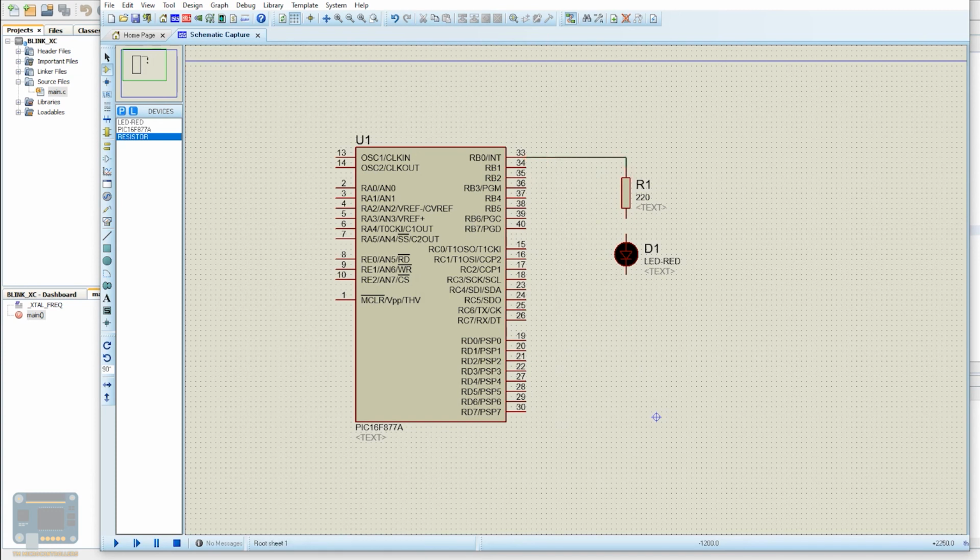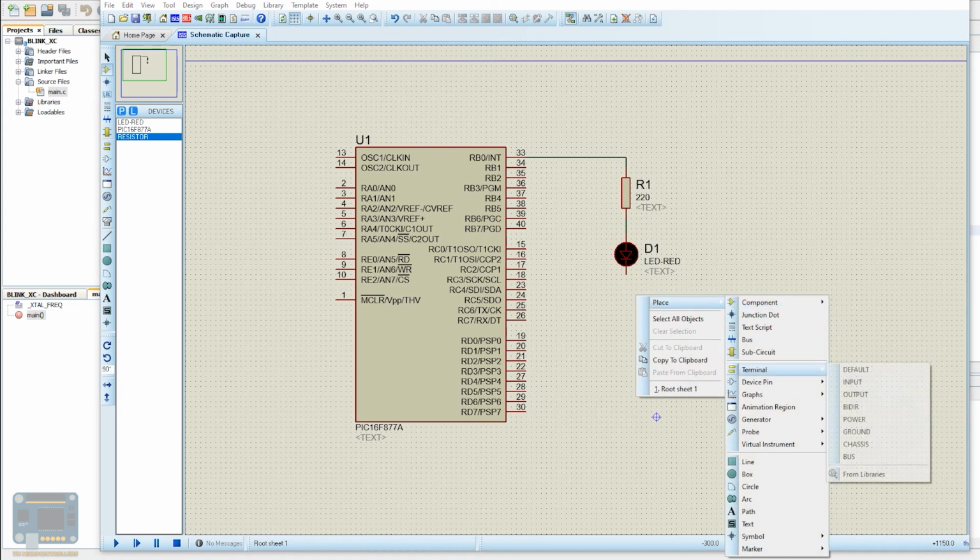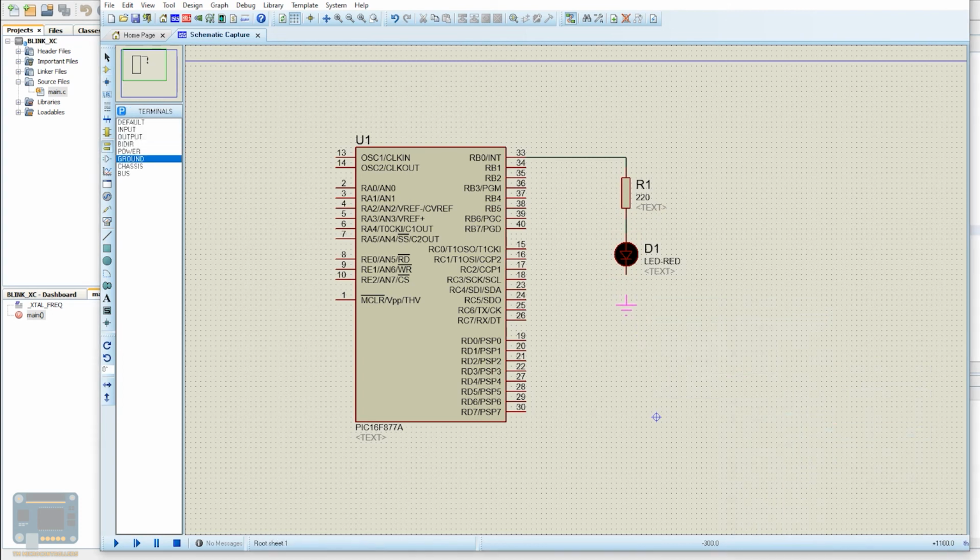By the way, the pin could produce around 25 milliamps of current. So if you would use no resistor in an actual circuit, of course, then with prolonged use, your LED might burn out. So it's really advisable to use a resistor in series. Just connect it like this, then of course you add ground, and you play.